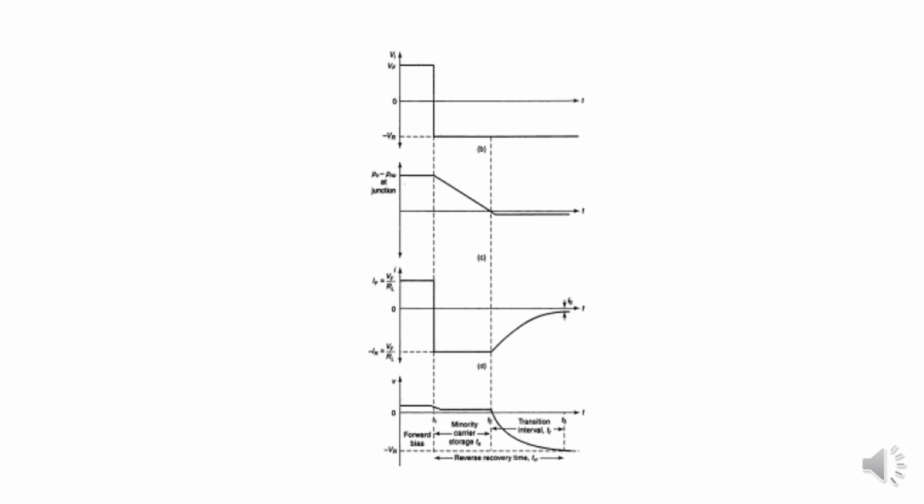When the junction transition capacitance across the reverse bias junction has got charged through the external resistance RL to the voltage minus VR. In order to minimize the effect of reverse current, the time period of the operating frequency should be minimum. And here the recovery time can be reduced by shortening the length of the P region in the PN junction diode.